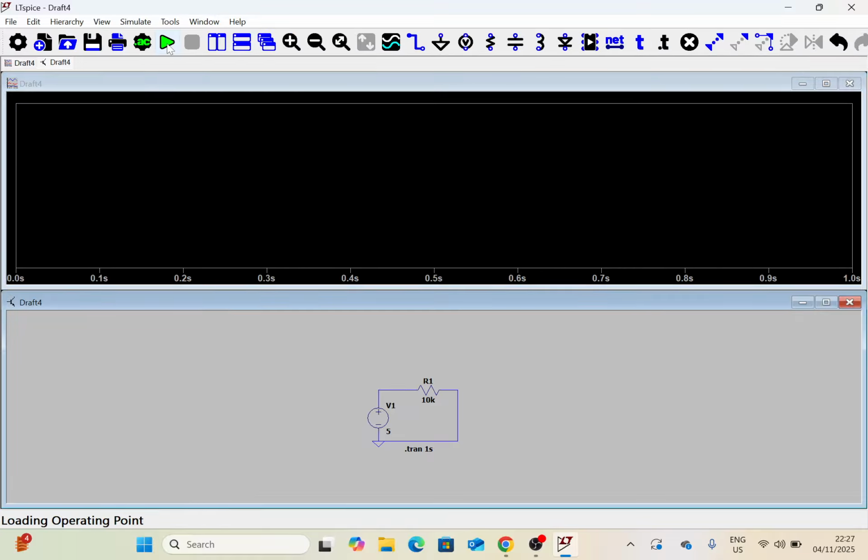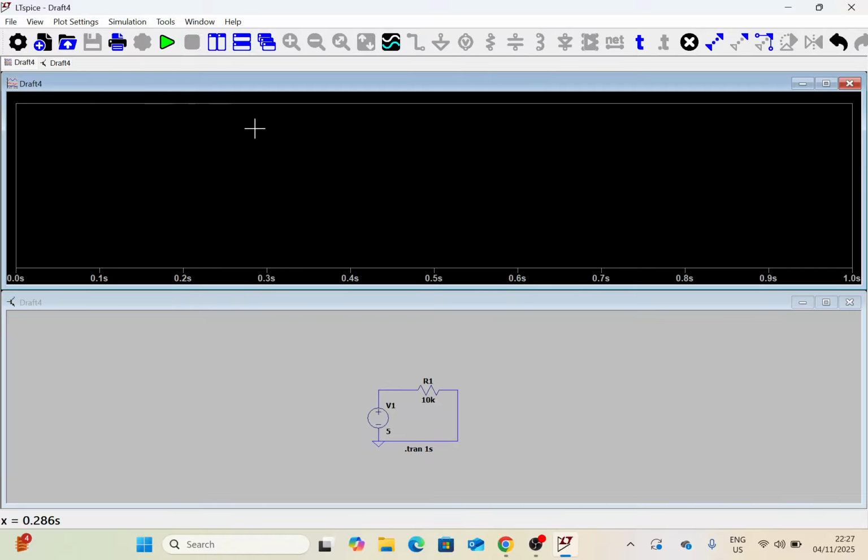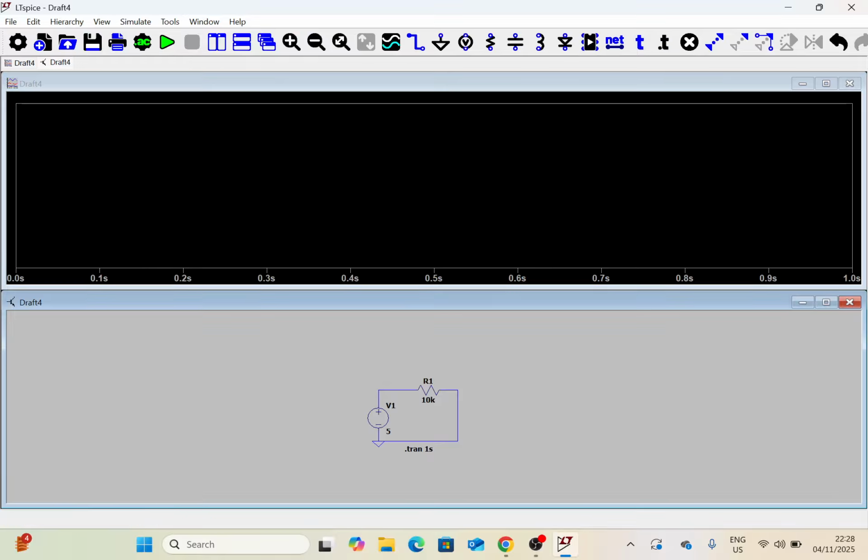All right, so now it looks boring, right? You click simulate and you are seeing this plot up here which doesn't really show anything, and then you have your circuit down here. But this is where things begin to get interesting, right? So if I hover my mouse pointer across any component, it is going to help you. This red probe is going to help you to probe the voltage at this particular point in the circuit. And then if you pass it on the component itself, you see that it changes.